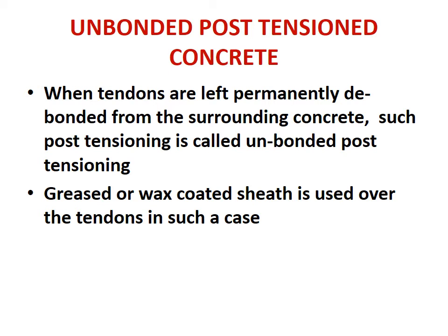In bonded concrete, the grout also saves the tendons from corrosion. In case of unbonded post tension concrete, corrosion is prevented by a greased or wax coating, so a greased or wax coated sheath is used over the tendons.